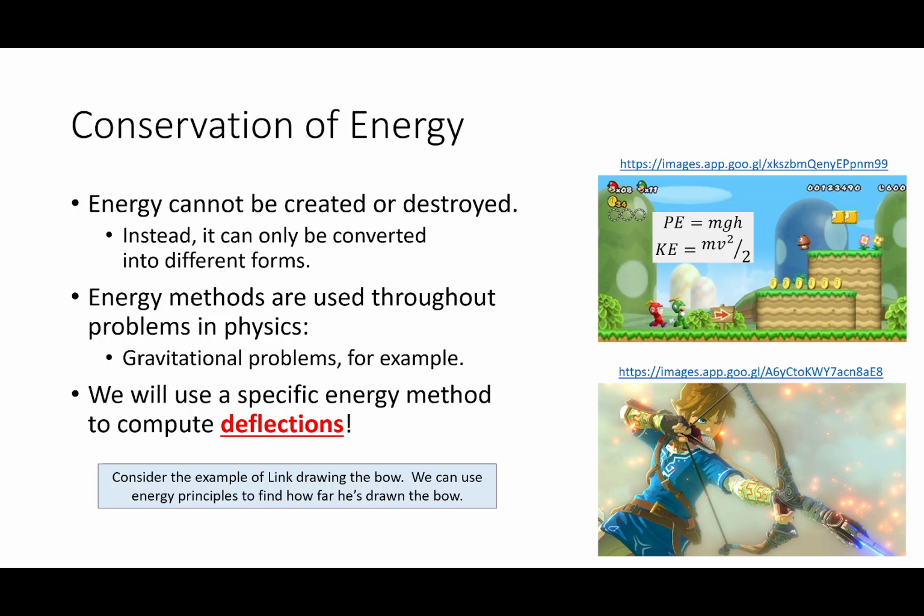The second event that happens is that the rubber band stores energy. If you have the rubber band in your hand, imagine that I said, here's the rubber band, I want you to yank on it and just hold it there for 3 hours. That's going to get kind of hard, right? Why? Because the rubber band has deformed, it has responded by absorbing that energy. Does that make sense? It's absorbed that energy. The more external work that you do to the rubber band, the tighter the rubber band is.